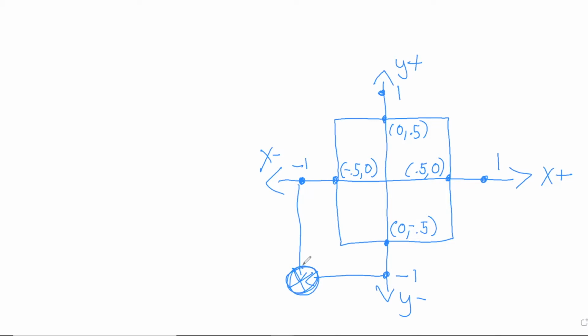We're going to talk about compensating for the radius. And then we're also going to talk about using cutter compensation, which will lead us into our next topic of this lecture. Cutter compensation will offset the center of our cutting tool and shift the tool automatically from some parameters that we give the machine.